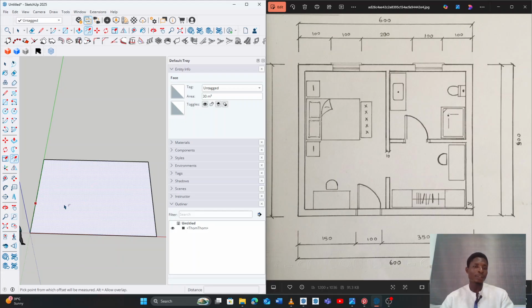To use it, you left click again. You have to make sure that your offset tool is on the surface of the object, and the red square box is on the edges.